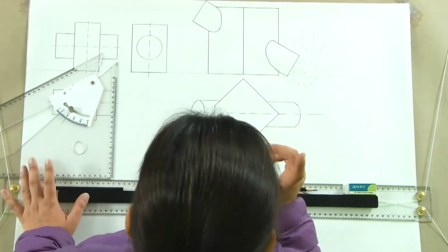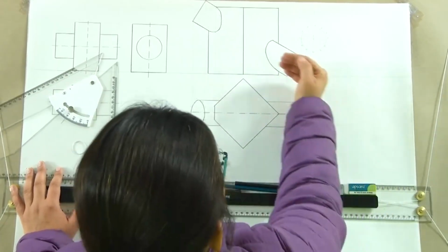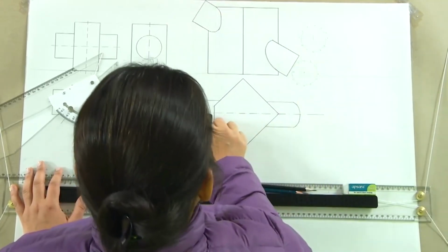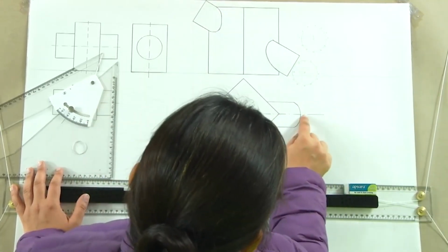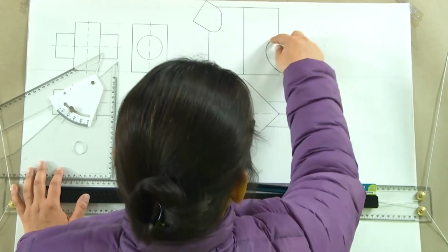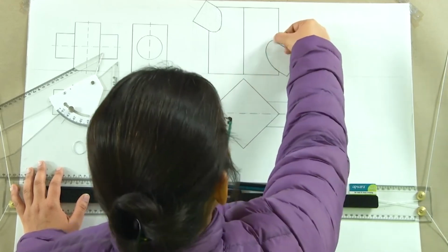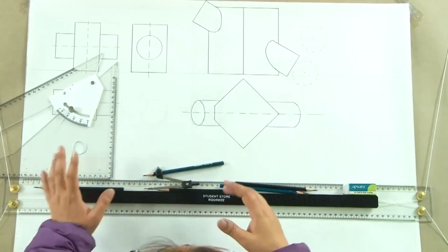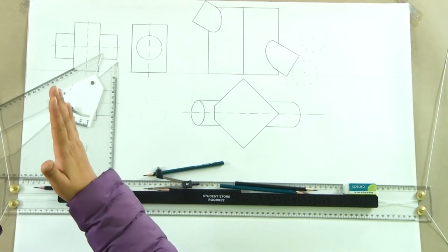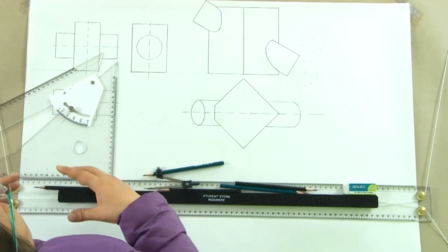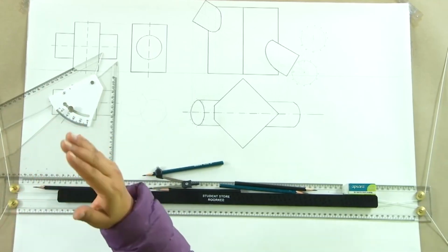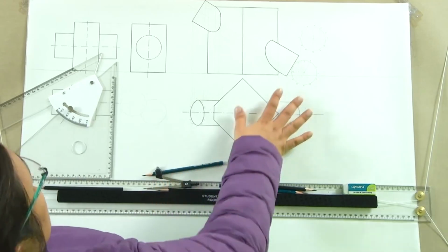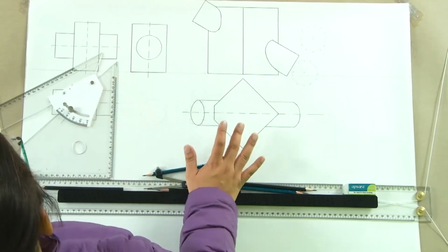Either way, what we have to keep in mind is that if the projector of 4 is here, it has to match with the projector of 4 horizontally. The projector of 4 will have to meet up with the projector of 4 in the top view. The projectors, whether they are coming from the vertical plane or the horizontal plane, will result in a point only when they intersect. So, keeping this fundamental in mind, this is how we would draw intersection of surfaces.